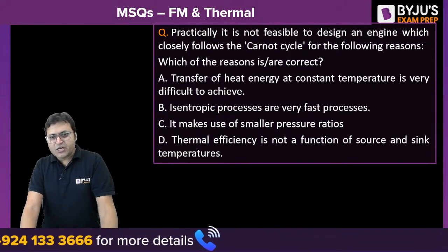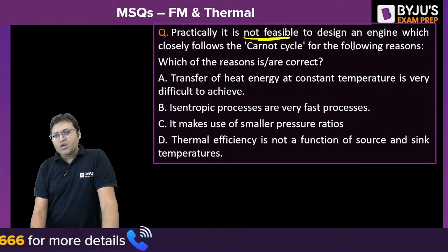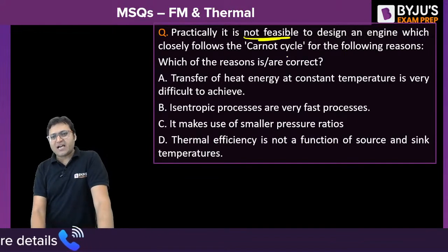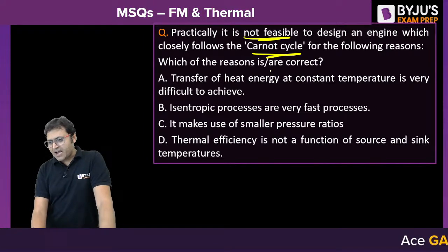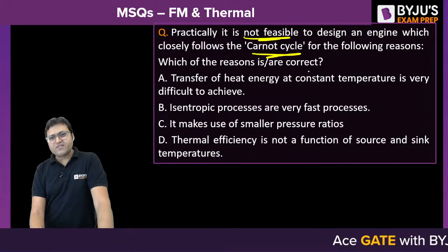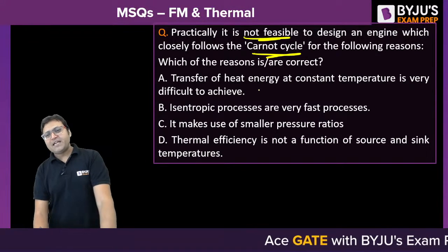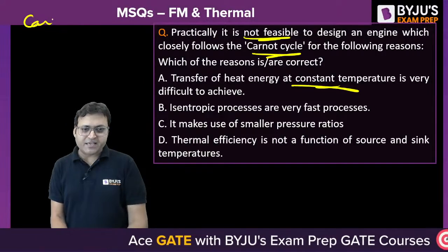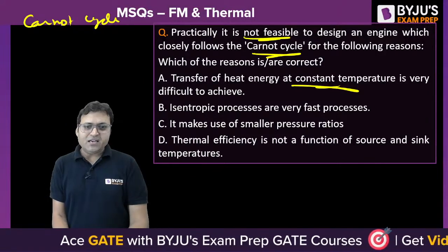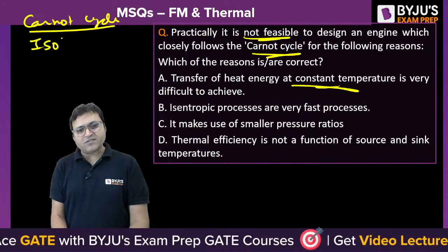Practically it is not feasible to design an engine which closely follows the Carnot cycle. Yes, that is true. The actual cycle cannot be the Carnot cycle for the following reasons. Which of the reasons is correct? Transfer of heat energy at constant temperature. In the Carnot cycle, it is isothermal heat transfer.